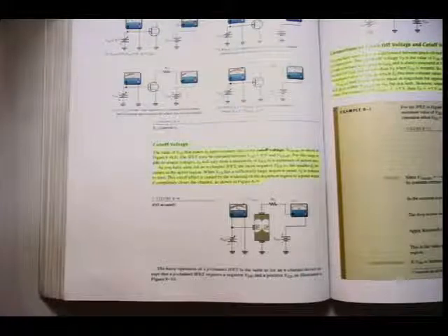As you have seen, for an N-channel JFET, the more negative VGS is, the smaller ID becomes in the active region. When VGS has a sufficiently large negative value, ID is reduced to 0. This cutoff effect is caused by the widening of the depletion region to a point where it completely closes the channel, as shown in figure 8.9. See, there we can see it.